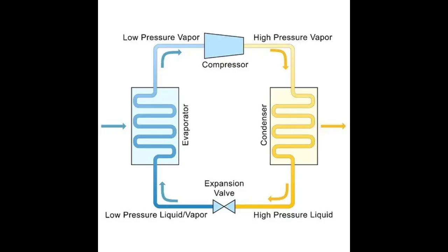The most important refrigeration cycle is the vapor compression cycle. It is the most widely used refrigeration cycle in practice. In this cycle, a vapor is compressed, then condensed to a liquid, following which the pressure is dropped so that the fluid can evaporate at a low pressure.